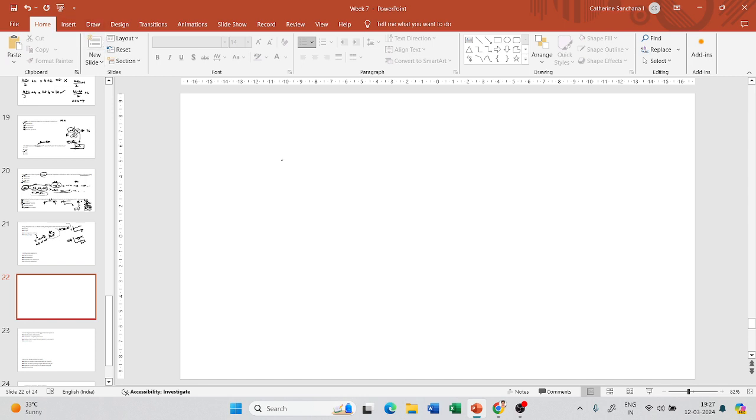If you see the energy dissipation equation for a viscoelastic material subjected to a sinusoidal loading, be it in stress controlled or strain controlled mode, this is the equation for energy dissipation, and here delta is the phase lag and not, as we saw, the deflection of the beam or anything like that, because here it is just a sample subjected to torsion, right?